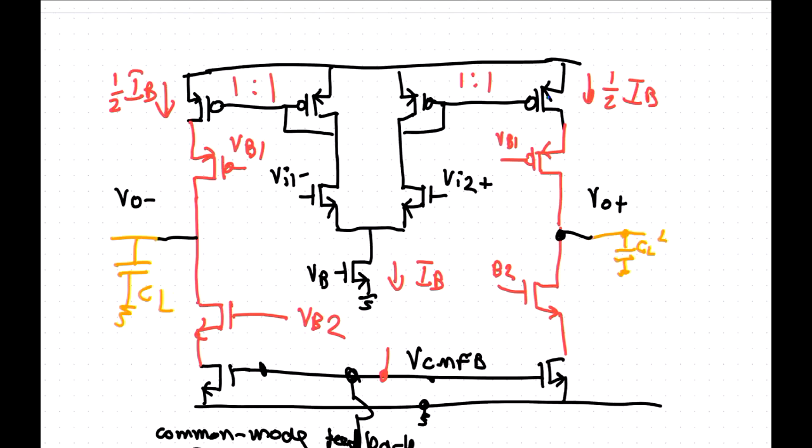And that means that from a differential purpose, I have now dropped the impedance down in this. The differential impedance now is the series resistance of those two. So unless I make those two resistors like hundreds of megaohms, something like that, this is not good, especially if I have the super gain stage at the output, like a really, really high output impedance. If I put in those resistors, my gain is just dropped down to nothing. So that's not good.